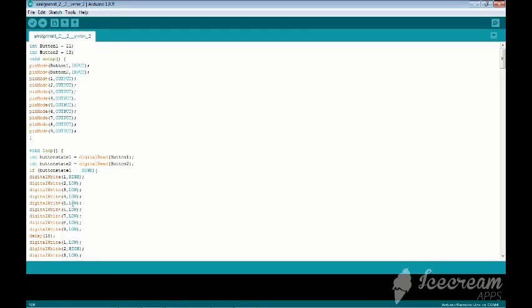For instance, this section tells that only LED pin number 1 will illuminate while the others go out. Throughout this sequence, it will project the pattern of the Night Rider lamp's movement, but twice as fast because the delay number is only 10 milliseconds.